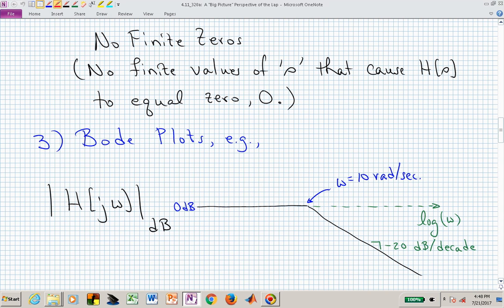Contrast that with the complex S-plane that we usually represent in a finite plane. There we can start at the origin, that's zero, and we can walk up the positive imaginary axis and take on different values of omega. The circus tent is now superimposed on top of this complex S-plane with poles, infinitely tall poles, located where the x's are. In this particular Bode plot, we now have a pole at omega equal to 10, or j10 in the complex S-plane.